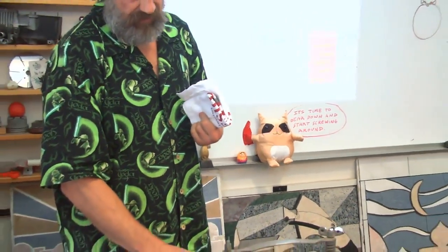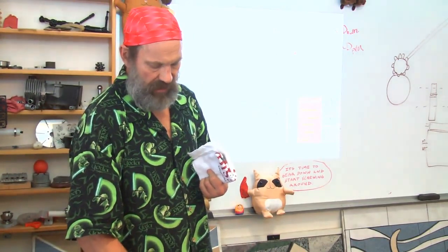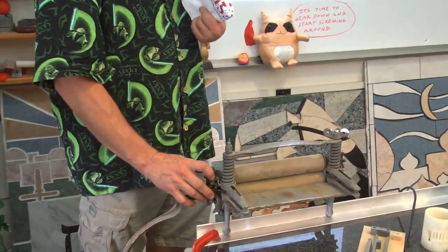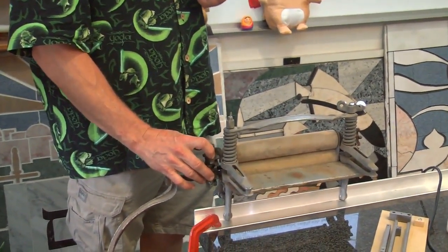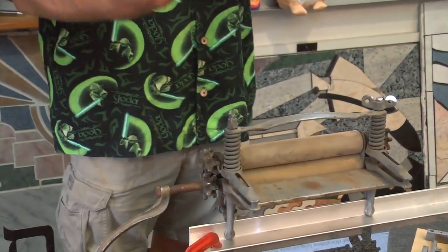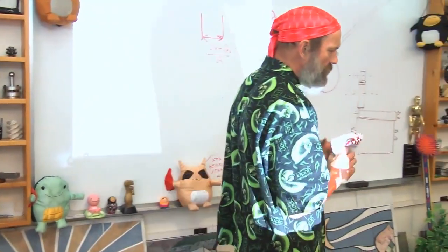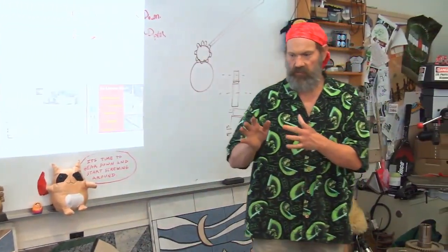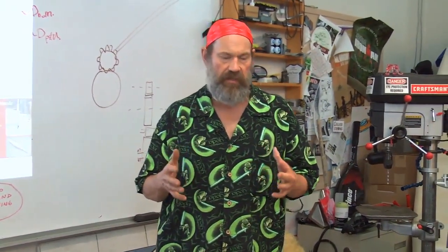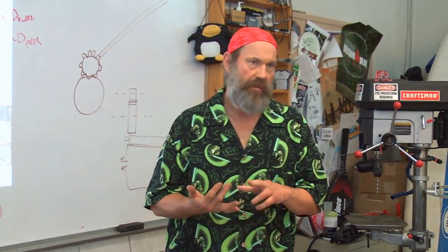So some clever person, 150 years ago or more, figured out that if you just had one set of chunkily made teeth that were too crunchy and that would skip and wouldn't engage well, I could use a second set at a half pitch away, so something is always engaged nicely. The reason that's so important is, one, this demonstrates how robust spur gears can be, but the other thing it demonstrates is that you can take relatively coarsely made gear teeth and make some really exciting prototypes and maybe even products out of them.